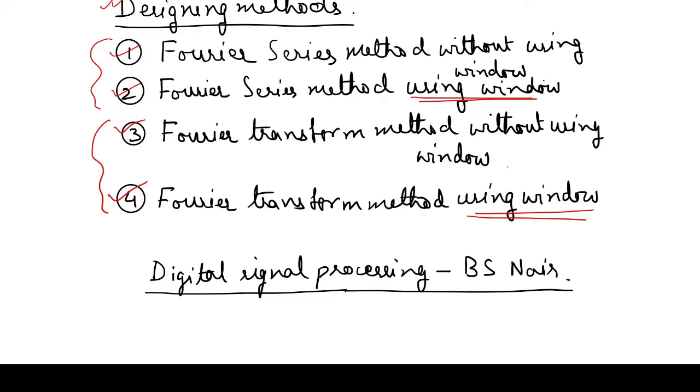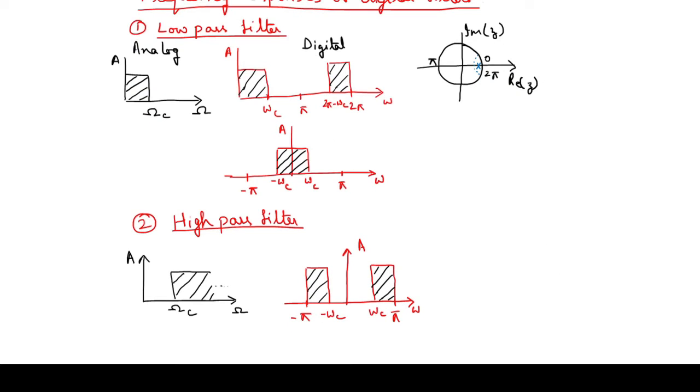So how is it reducing the Gibbs phenomena? That is the important thing. We need to remember that when we discuss the desired frequency response, we have brick-like structures, right? So there is a sudden decrease or sudden increase in the response, and we do not want that.